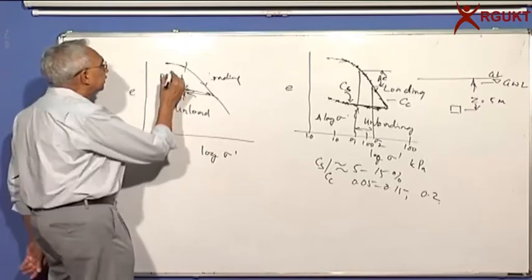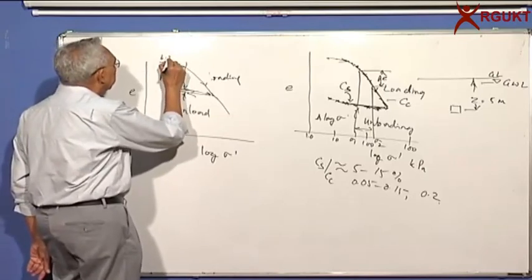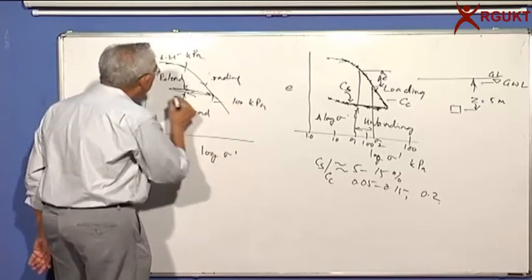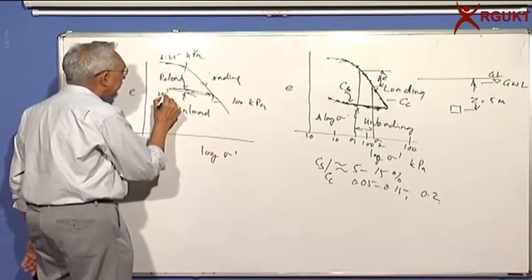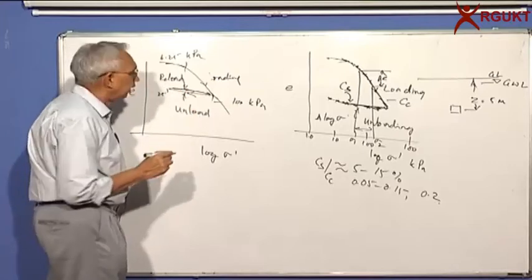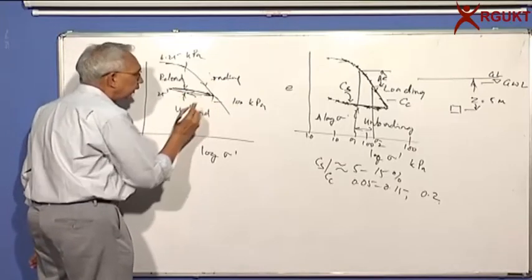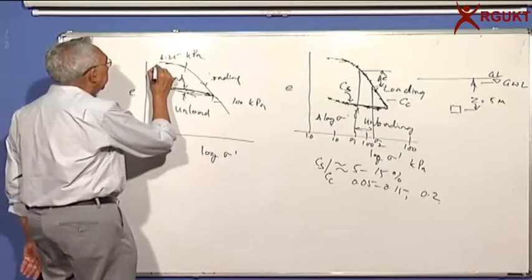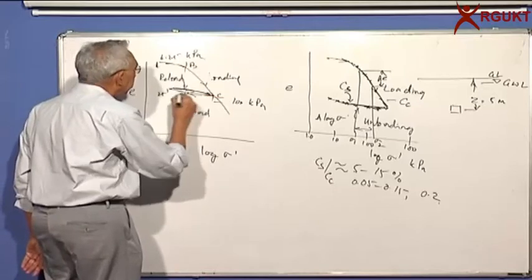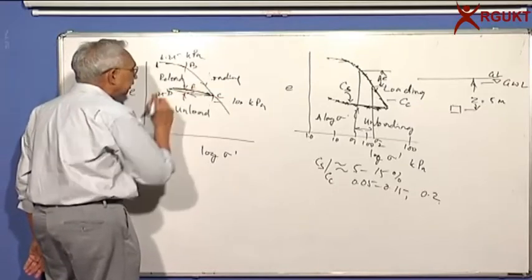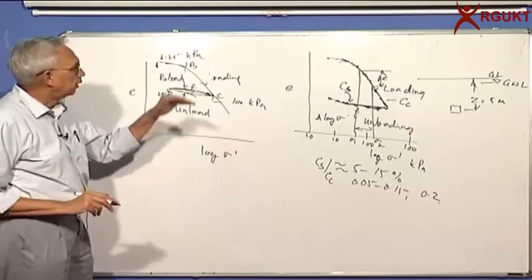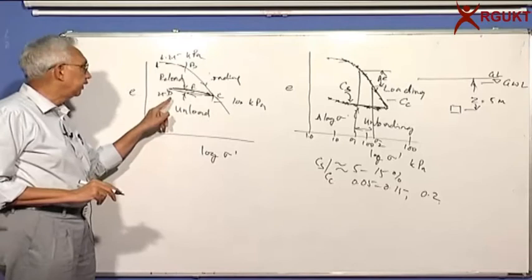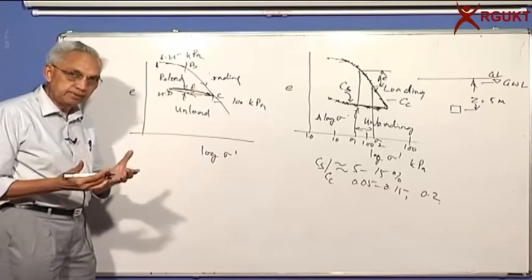What you have done is started with something like, let's say 6.25 kPa. You have gone up to, let's say 100 kPa. Again come back to maybe something like 25 kPa and reload it. There's a slight loop here, but what you find is this reload part of the curve, A, B, C, D, and let's say E. A to B is flat, B to C is very steep, C to D is again flat, and D E C is again flat.